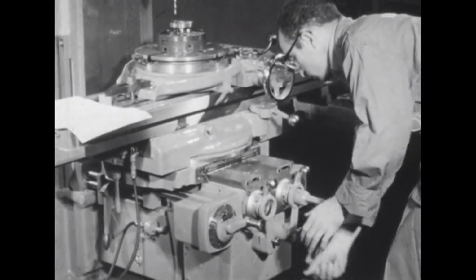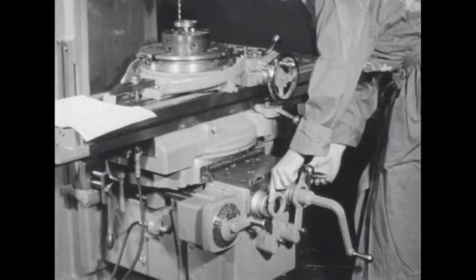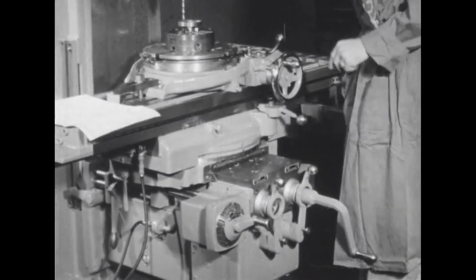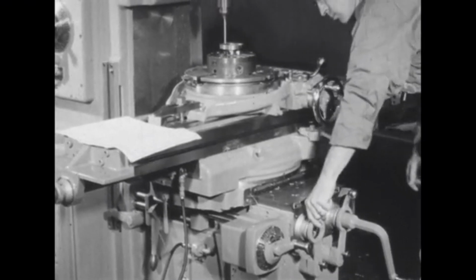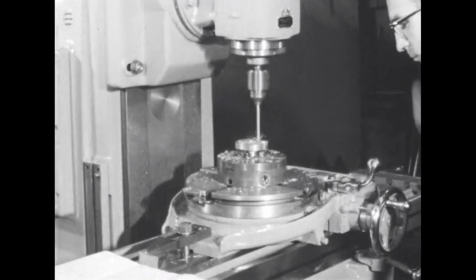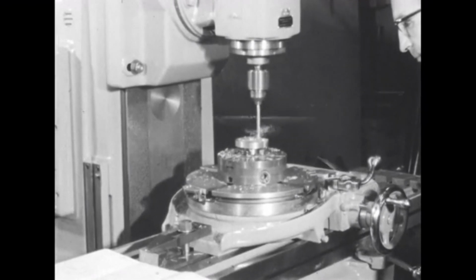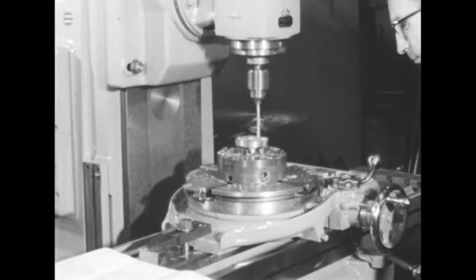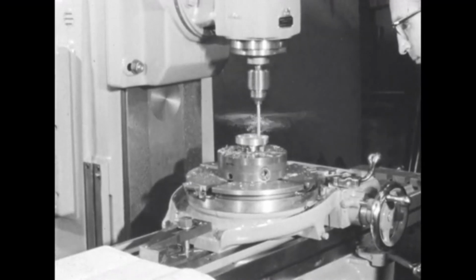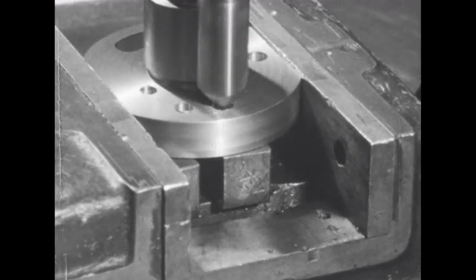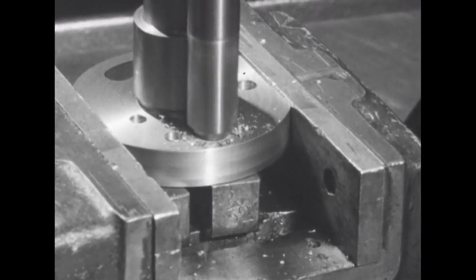There are 3 dials, 3 lead screws, and 3 hand cranks on a milling machine for moving and locating the table in 3 directions. The workpiece has been located for one of the holes, and the drilling is now in progress. The part has been moved to a drill press, and one hole is being countersunk according to the drawing.